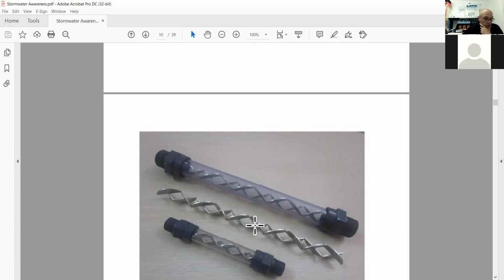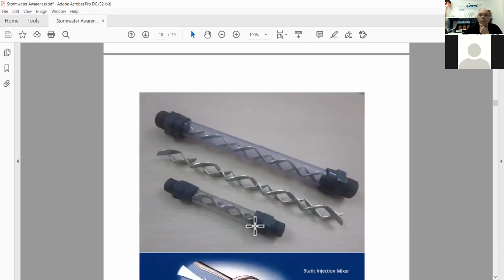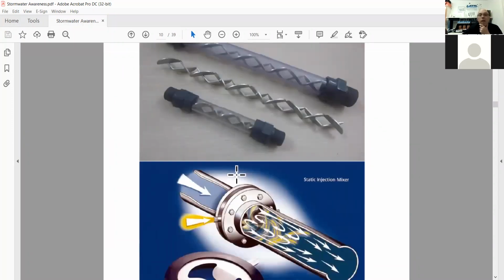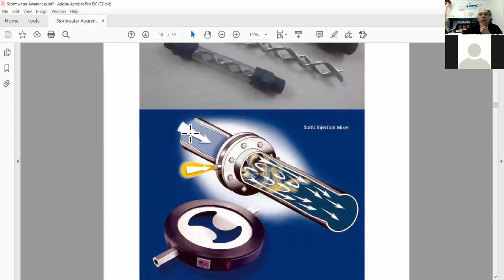All right, so dirty water is collected where some of the heavy solids settle out, and then this water is bench tested to find the best starting dose. With the dose known, the water is pre-treated using a static mixer. This is a photo here of a type of static mixer. Essentially, you end up with your polymer mixed 100% through this tube. Here's another style. You get 100% mixing, and very good diagrams showing you what's going on here. The water folds on itself.